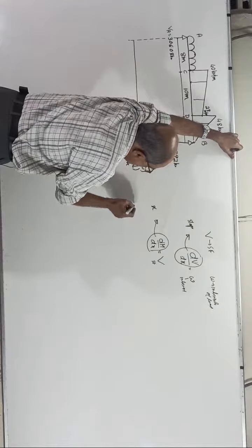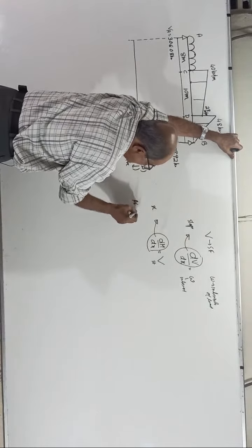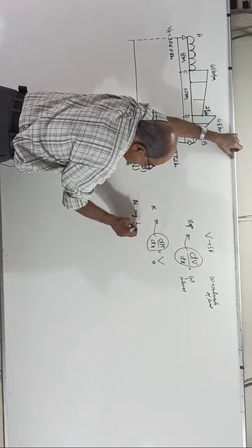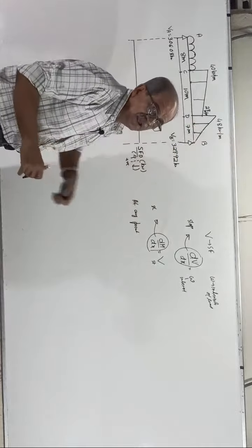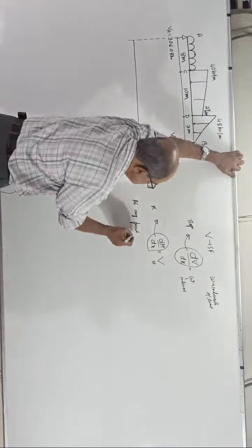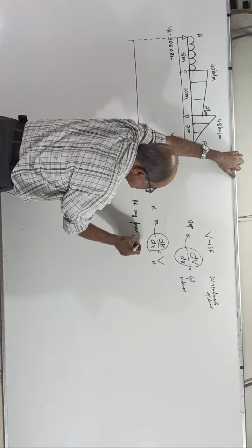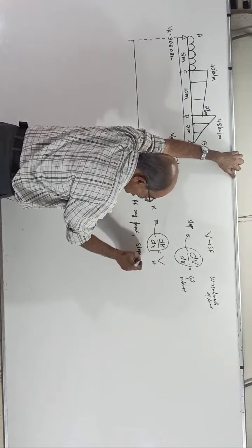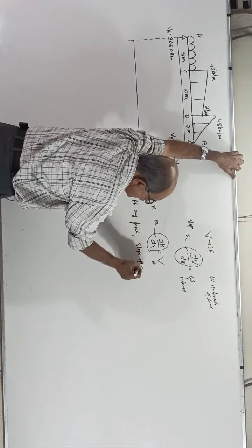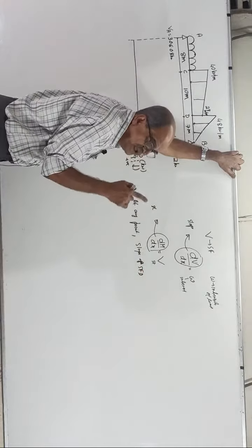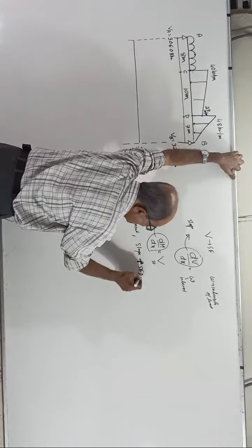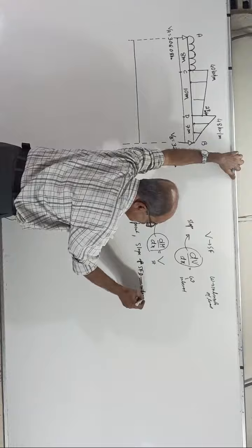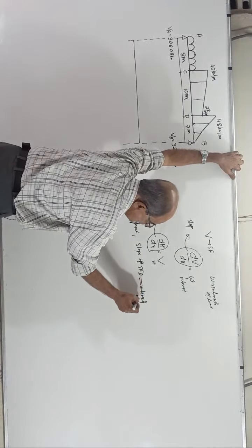Therefore, remember, this is applicable anywhere, at any point. See, the slope of the SFD is always equal to the intensity of load.